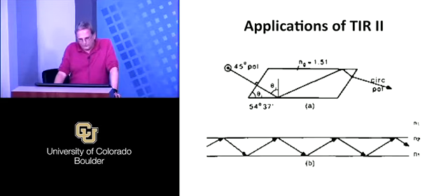These days, with fiber optics and other things, putting in a bulk component that costs thousands of dollars seems insane. But there was a time when these things were reasonable, and there are systems where they still are. But this can be very low loss. Again, you can anti-reflection coat the input and the output facets, and you can get near 100% throughput of highly polarized, accurately polarized light.